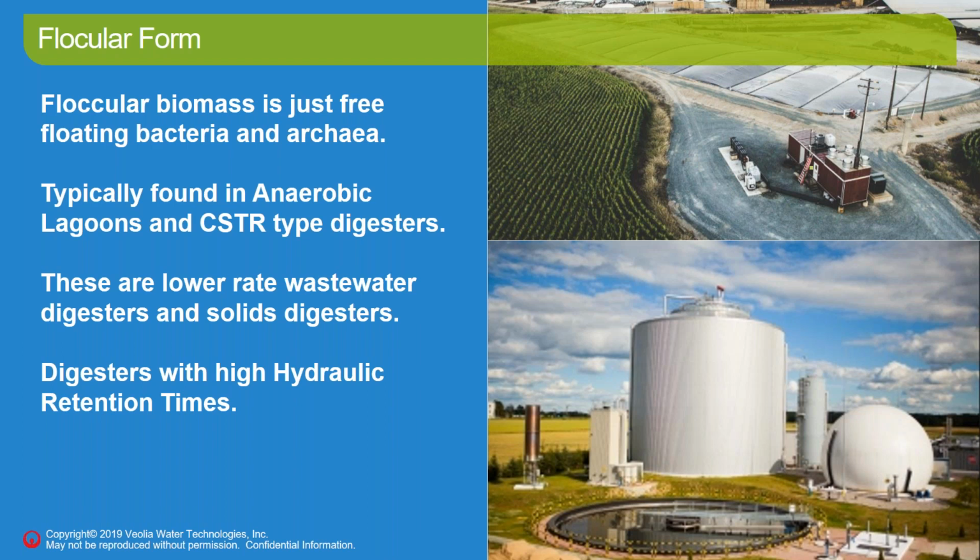And they're typically found in anaerobic lagoons and CSTR type digesters. CSTR, again, is continuously stirred tank reactors. And the lagoons and CSTRs are typically lower rate wastewater and solids digesters. They're digesters with high hydraulic retention times. So it's usually a hydraulic retention time well over 3 days, or a solids retention time, if you're digesting solids, over 3 days.